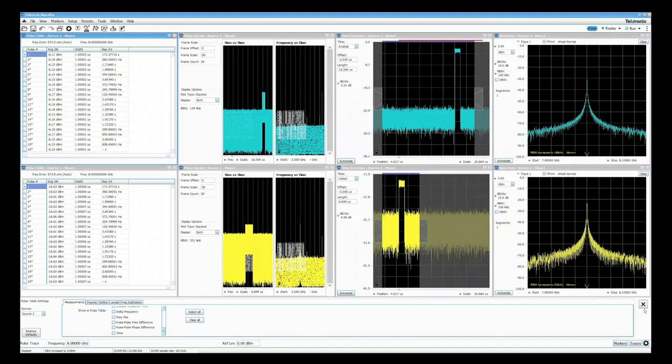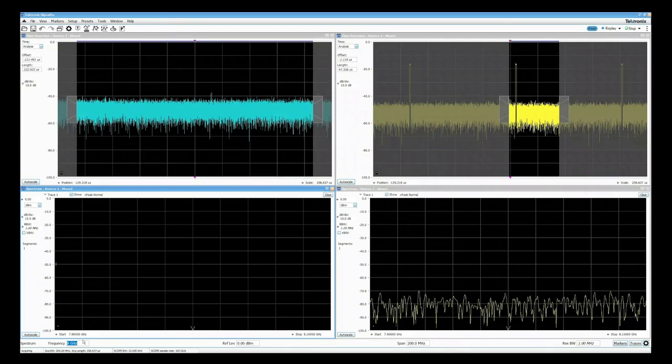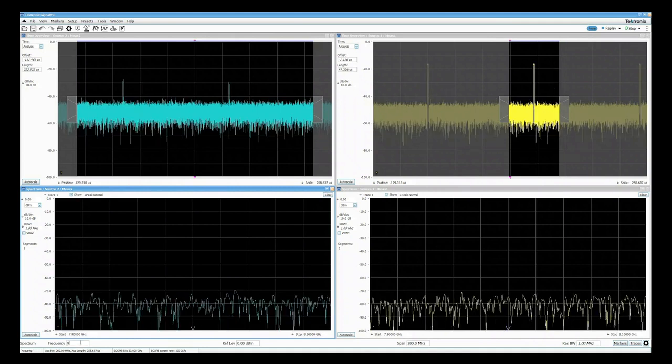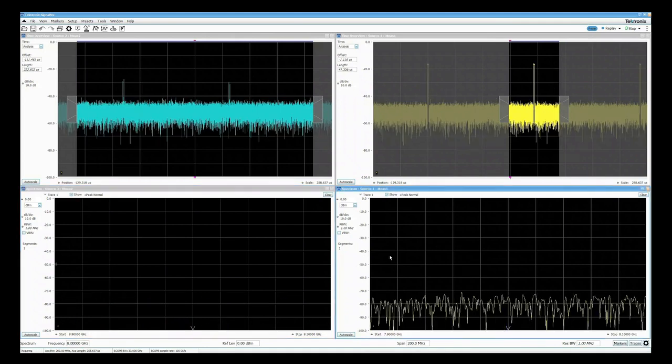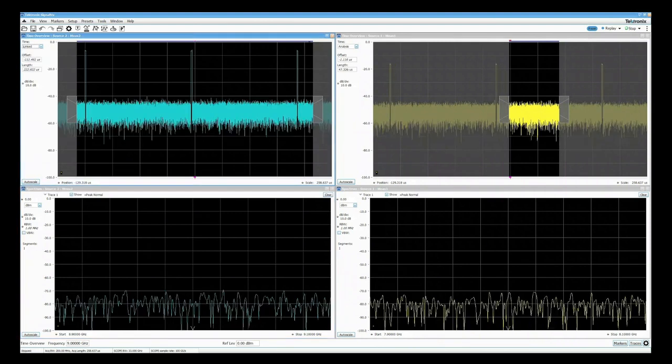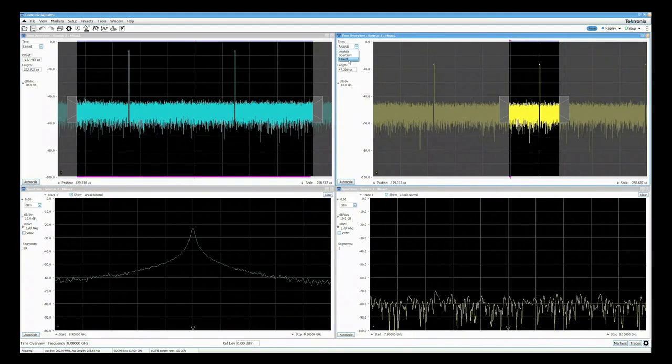For MIMO radar, the signals are orthogonal by utilizing distinct center frequencies for each element. Therefore, center frequencies for each channel in SignalView need to be configured independently. Settings such as center frequency, span, and RBW for each channel can be adjusted independently.